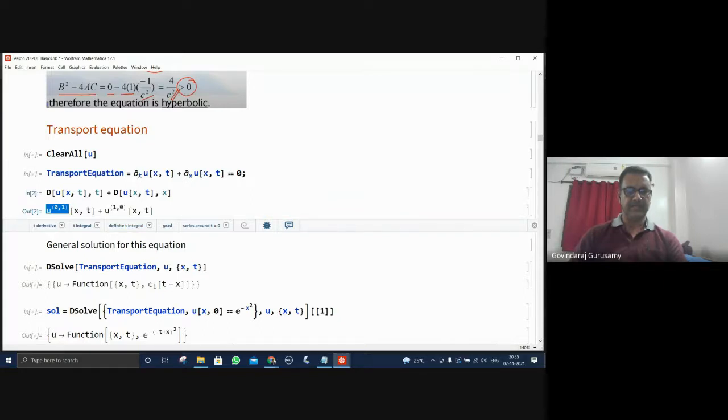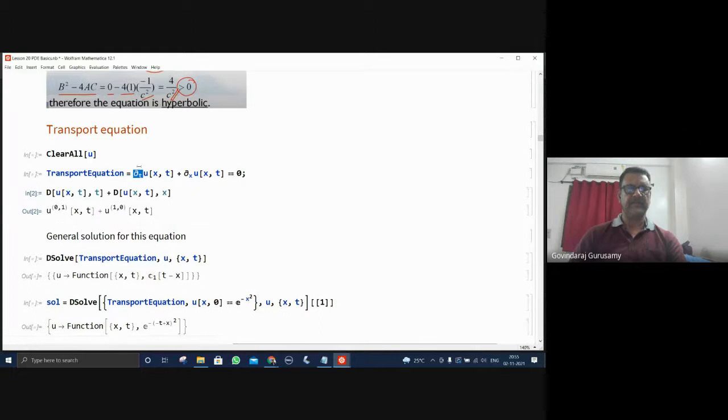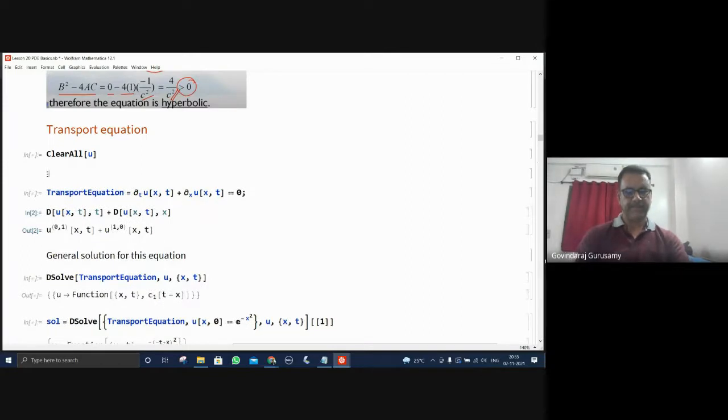That can also be written as ∂ with a subscript, which you can write by using escape, pd, escape again. Then afterwards you press Control underscore, then add this subscript. That's all. Then afterwards, your variable.